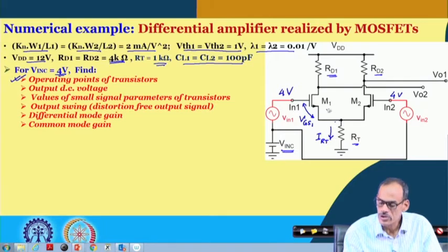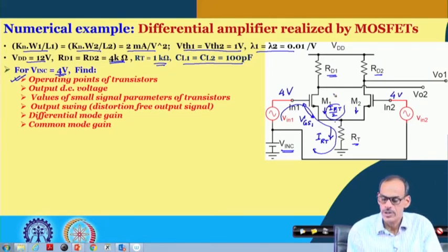And again because of identical transistors M1 and M2 and RD1 and RD2, the currents are getting equally split into 2 branches. So, this is I_RT by 2 and so on. So, if I consider this loop and if this voltage is given to us, from that we can find what will be this current, or we can say what will be the corresponding IDS current of transistor 1.